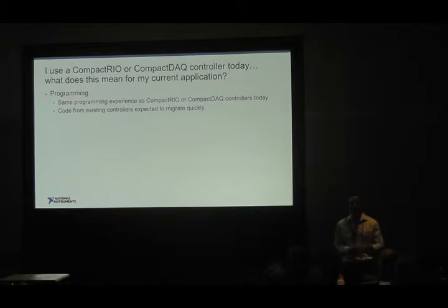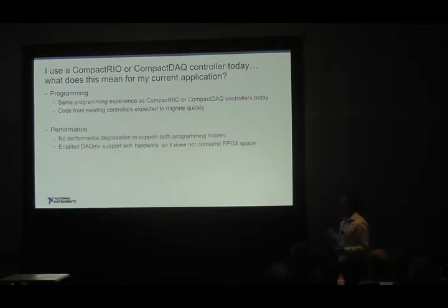If you're a CompactRIO user, you're still using LabVIEW Real-Time, LabVIEW FPGA. If you're a DAQmx user, you're still using DAQmx to be able to get your data acquisition across. And then from a performance perspective, you're not going to see a performance hit by integrating these two technologies together. Specifically, in order to make this happen, we did this change at a hardware level. We didn't just implement some of the DAQmx functionality within the FPGA. It's a completely separate ASIC that allows you to go in between the two of them.